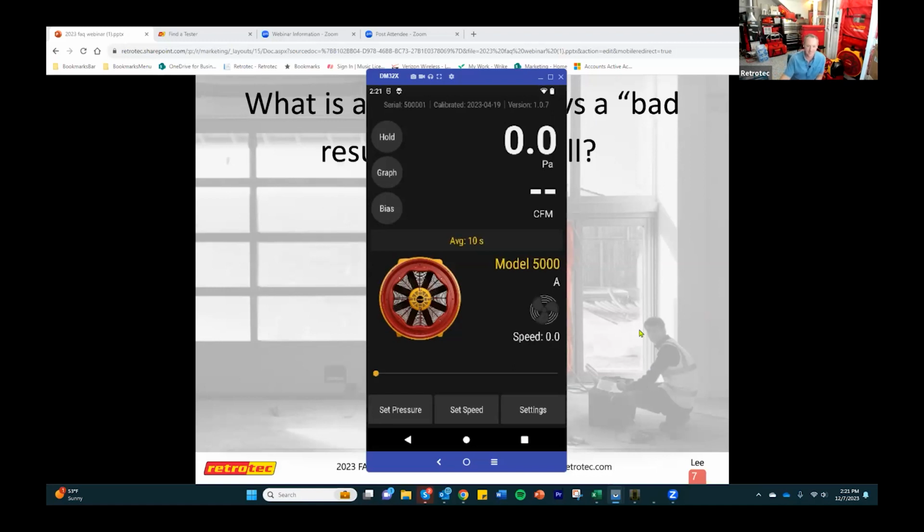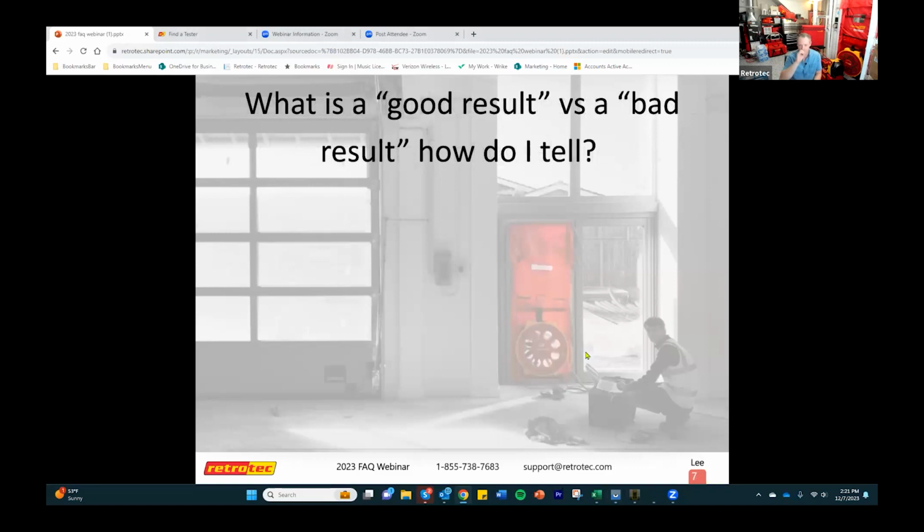Definitely, and that's perfect. And the comment you made about not wanting to use ACH in a lot of cases, that envelope area is what commercial envelopes typically use. And I believe that's because as the building gets larger, your envelope area doesn't grow as fast as the volume. So larger buildings are going to have larger amounts of volume, which is going to dilute any leakage you have.